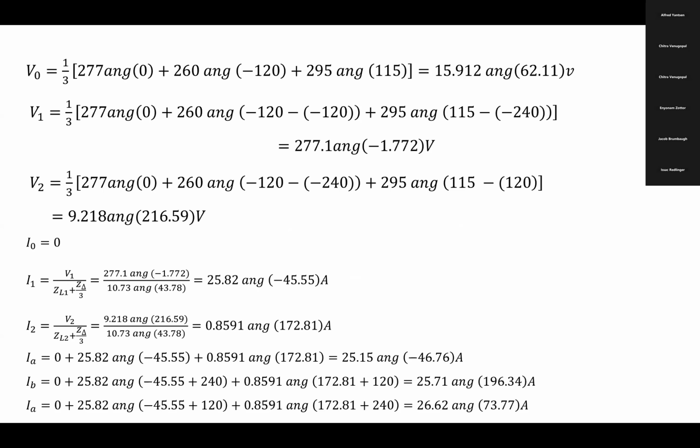And then from I0, I1, I2, calculate IA, IB, IC. Here you can see all three are carrying almost the same magnitude. The angles are different. That shows it's a different phase, because there is no fault hitting the system. If the fault hits the system, then you will see different values here and the angles are different. That can tell you what fault it is.